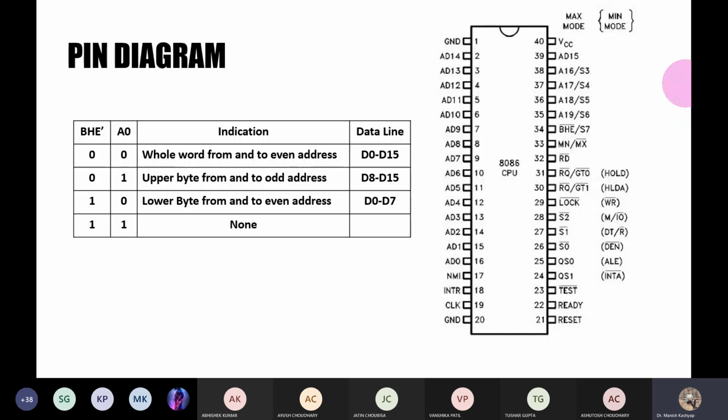You have to provide the base address as well as the offset address. And the second fact is you will be able to read two memory locations at once in the best case in the 8086 CPU. Sometimes you will be reading two memory locations at once and sometimes 1 byte per instruction. So for that decoding part, this will be very useful when we make the hardware circuits where the external things will be connected to this processor, right?